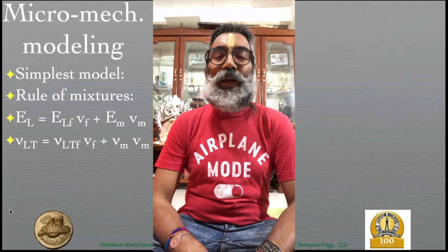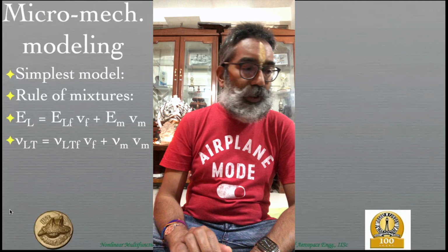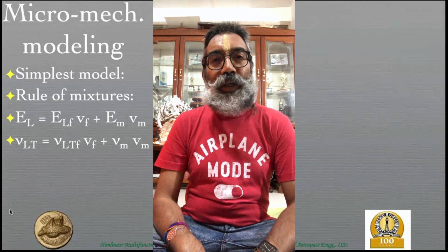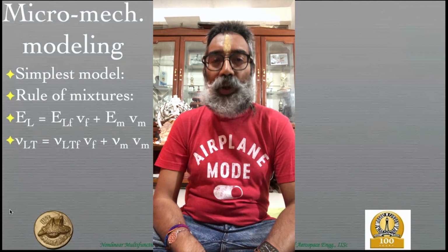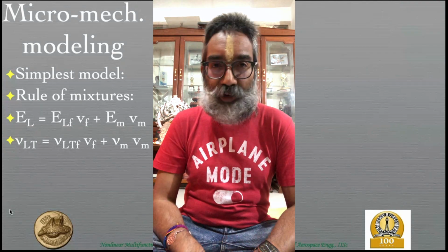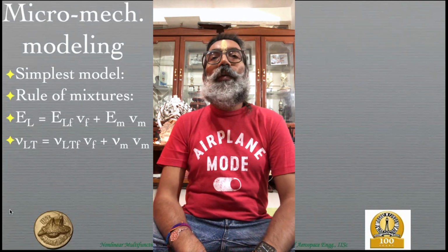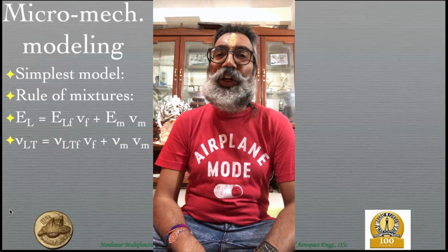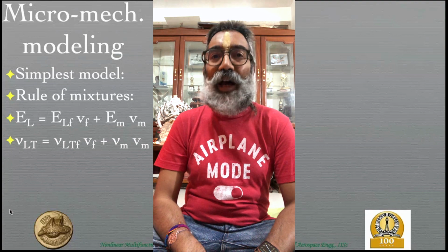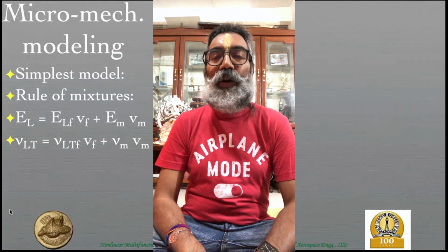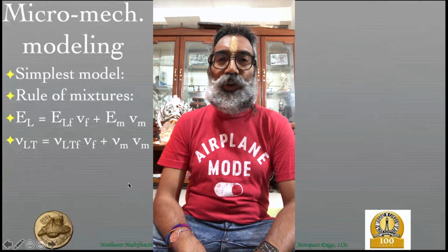And the reason why that negative sign comes is because in the denominator you have a 1 plus nu, and as nu approaches -1, the shear modulus would become infinite. Similarly, you can show that the bulk modulus would approach infinity as the Poisson's ratio approaches plus half. There is plus 0.5, and therefore that is the upper limit that you have.